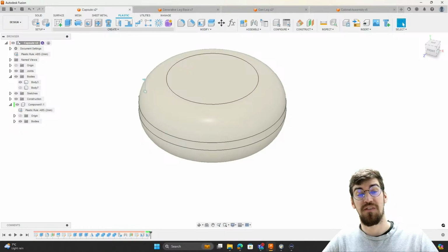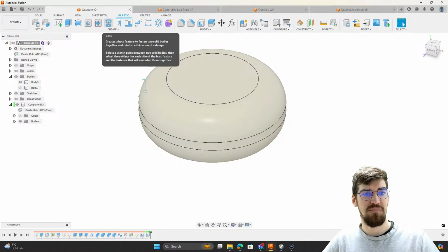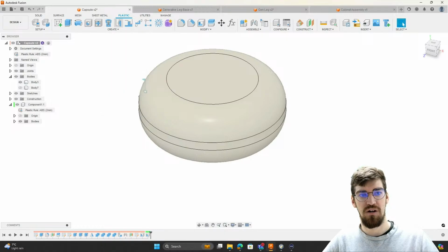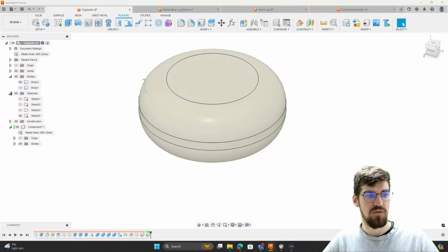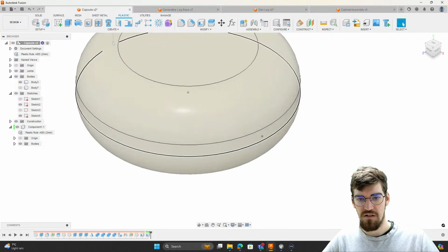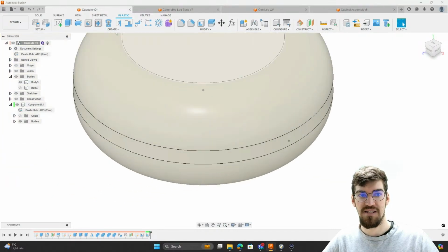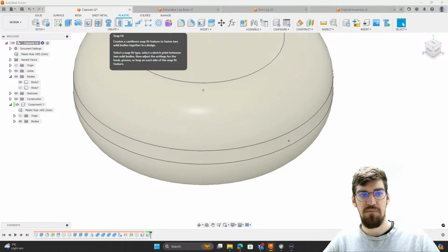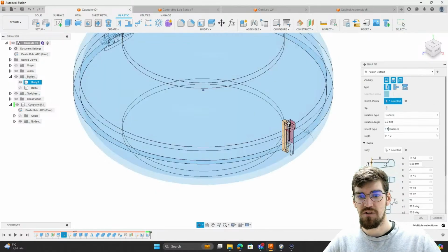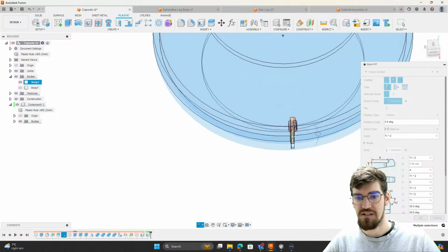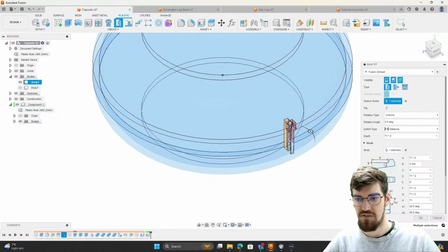We've also got some automated modeling sides to the product design extension. So we've got the ability, as I mentioned before, to create bosses and snap fits. These are each driven by sketches, so sketch points within the model itself. I've got one in the background over here somewhere. This one over here seems to be the one. And you can see I've got a small point in the sketch itself within Sketch 2 that I'm going to use as a reference for the location of my snap. If I grab the snap fit option from within the create panel, it'll immediately place a snap fit exactly at the point which I've selected over there.